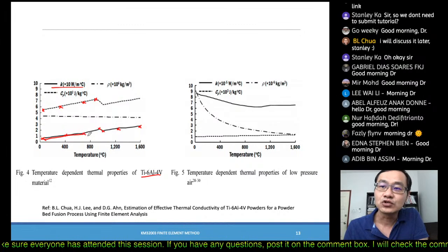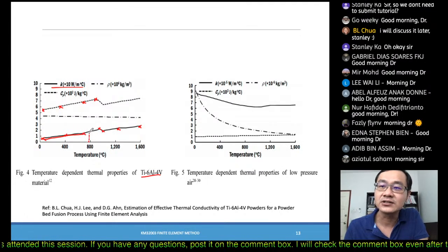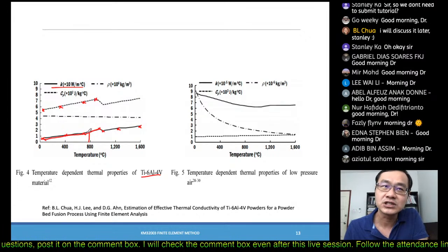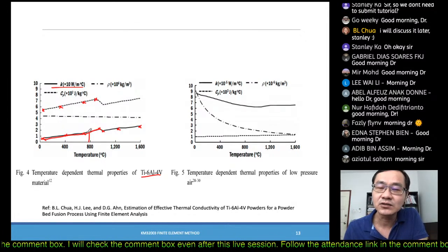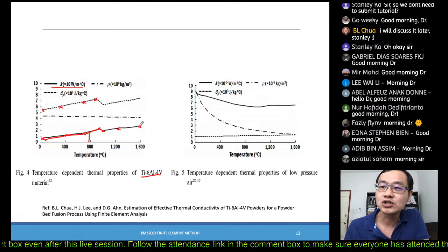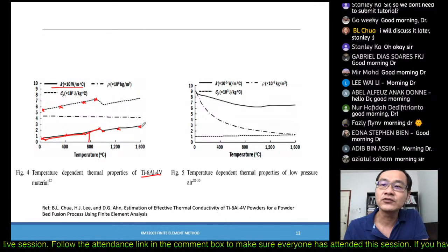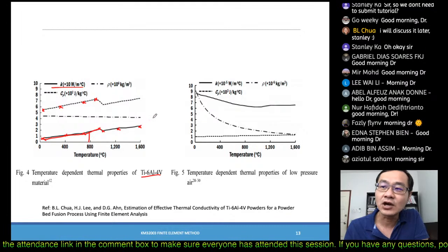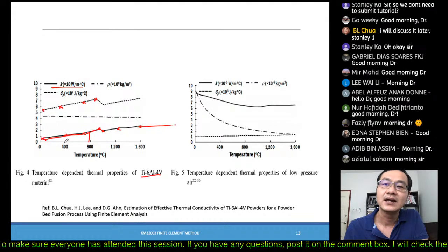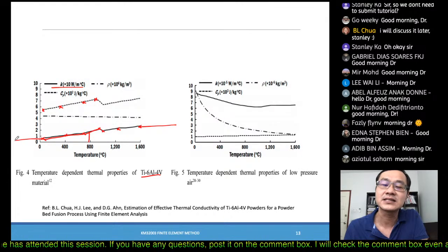Let's say the temperature is 800, they will interpolate using these two points and put this thermal conductivity into the equations and calculate. However, when it reaches the end, the software doesn't have another point to interpolate, so it will just take a straight line, similar to the end.